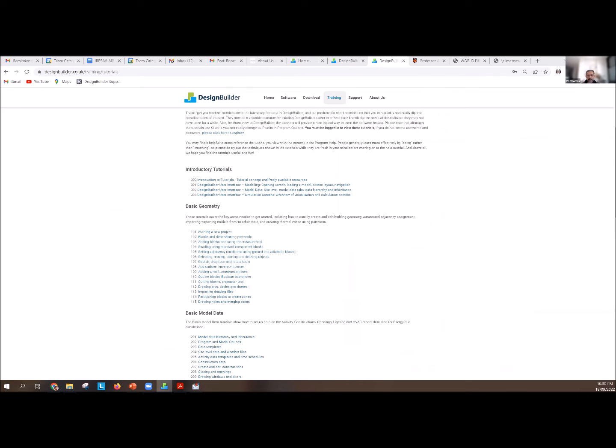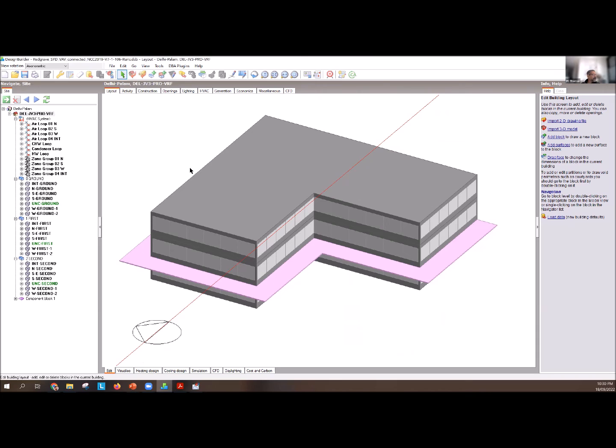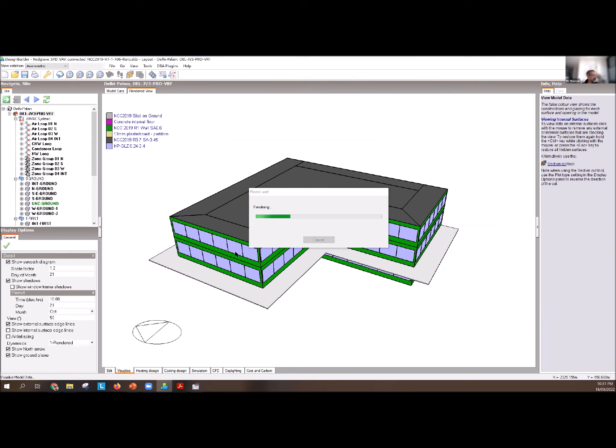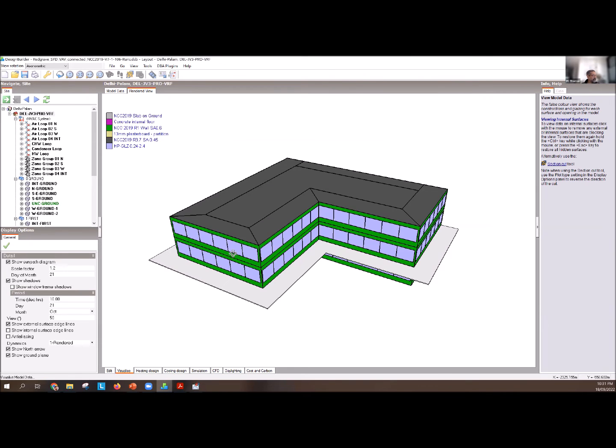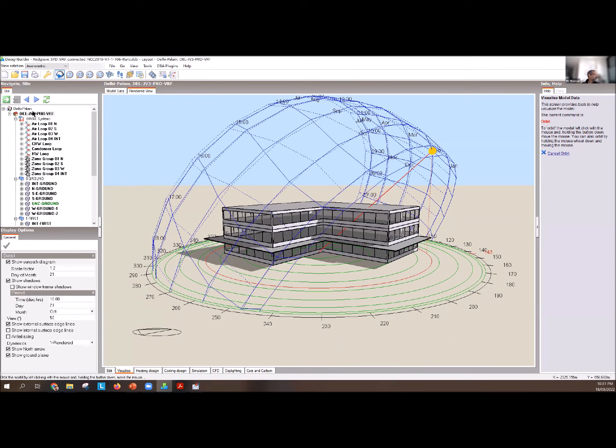When you model a building, like here you go. I've got a building here. You have the overall building. Dark gray is opaque, light gray is windows, pink is shading, right? If I want to, I can turn on these visualization modes. That one tells me what materials have been put on the building. And if I go to the rendered view, then you can see how the sun path works in this building. Okay. And I think I've got Delhi here.